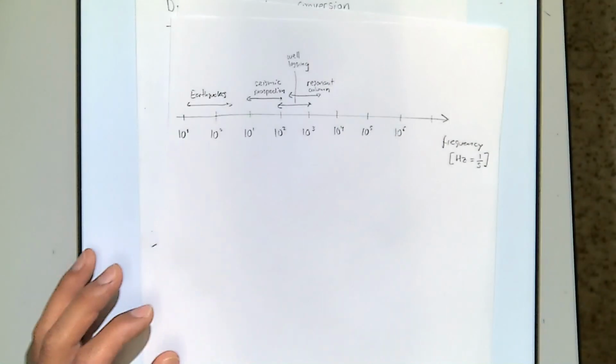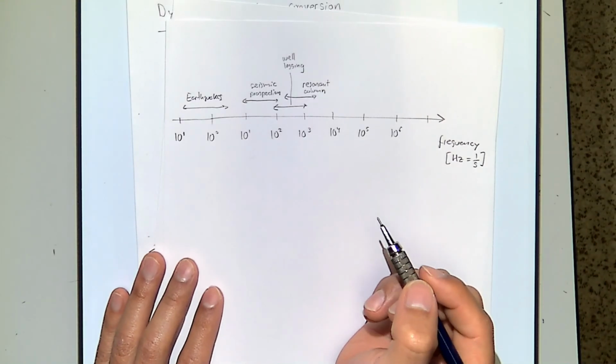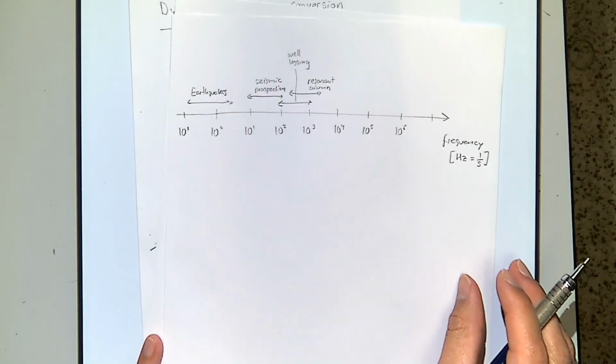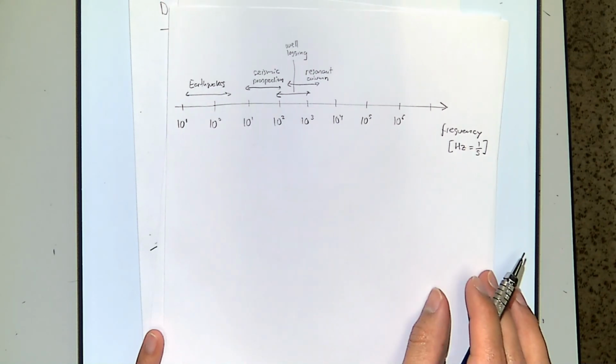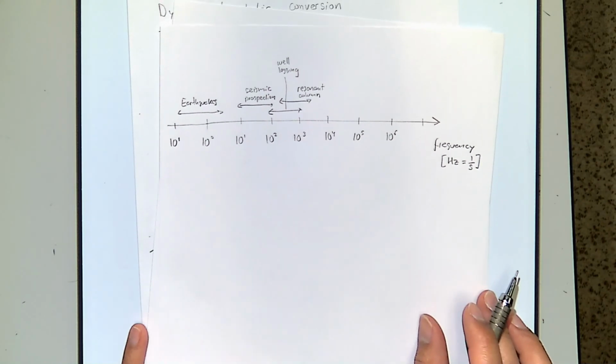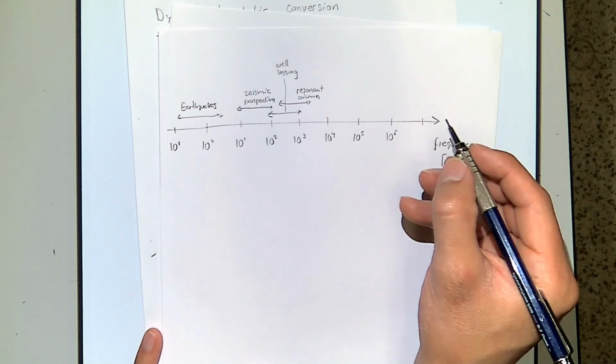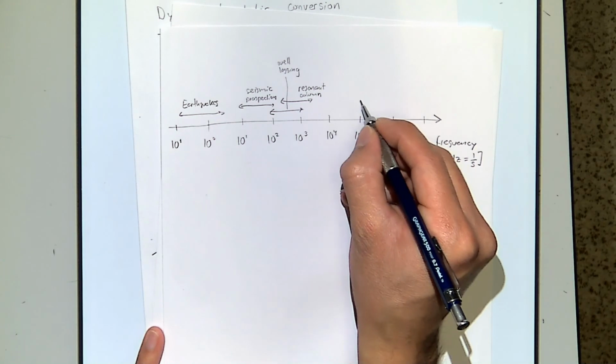A resonant column is a device in which you have a sample and you apply torsion, and you measure the torsional shear wave, which gives you the shear wave velocity. It was invented by a professor here at UT called Ken Stokoe. It's a very smart device. What about ultrasonic velocity in the laboratory? It's more or less in the order of kilohertz to megahertz.